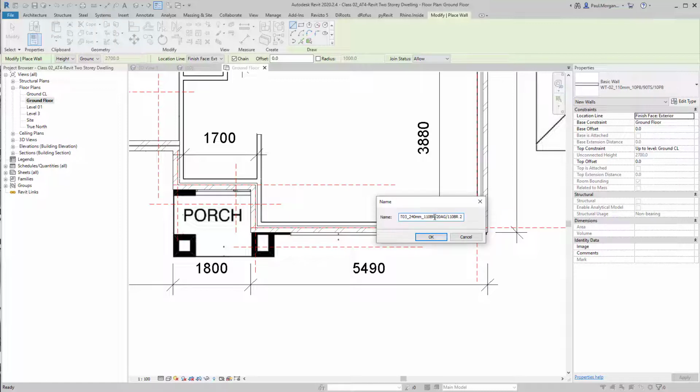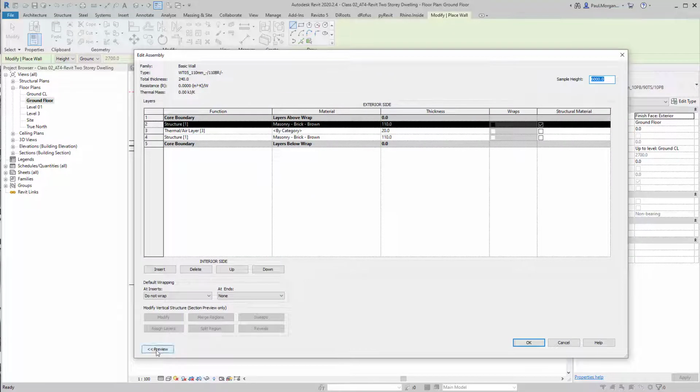And we're just going to get rid of everything else. Like so. So this will be wall type 5 now. Wall type 5 will be 110 mil wide, and it's going to be created with just 110 mil brick, nothing more, nothing less. So I'll say okay, and then we'll go to edit, we'll edit that structure. So I'll bring this over here.